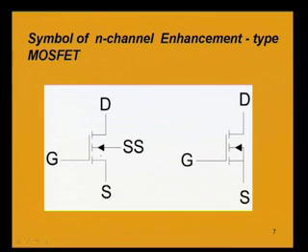junction, significantly reflected by this symbol, and this symbol is for external connection of the substrate terminal. If we have internal connection of the substrate terminal between the substrate and the source, then we have this symbol, because here we are showing that the substrate and source are connected.